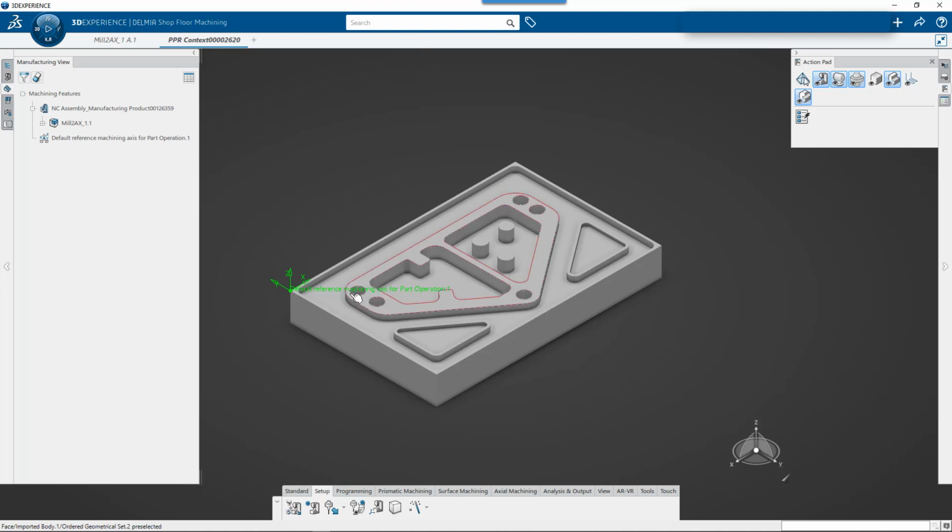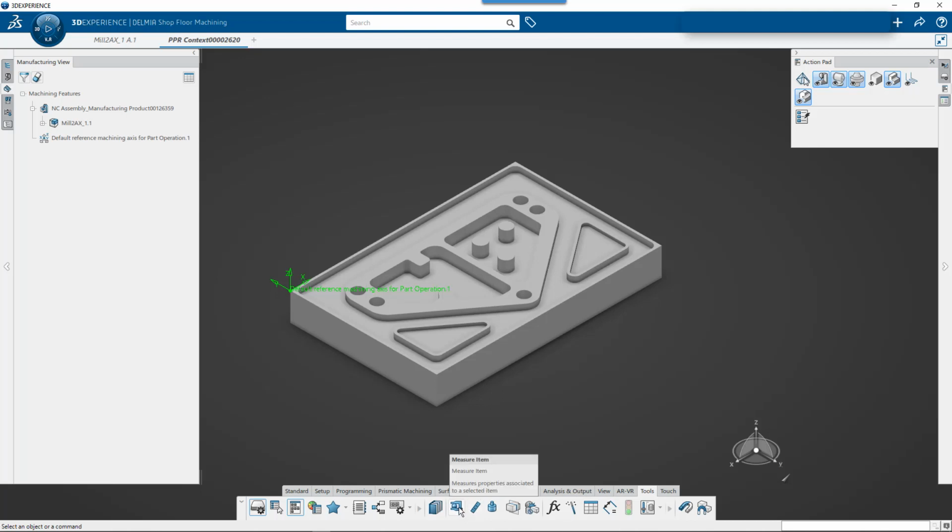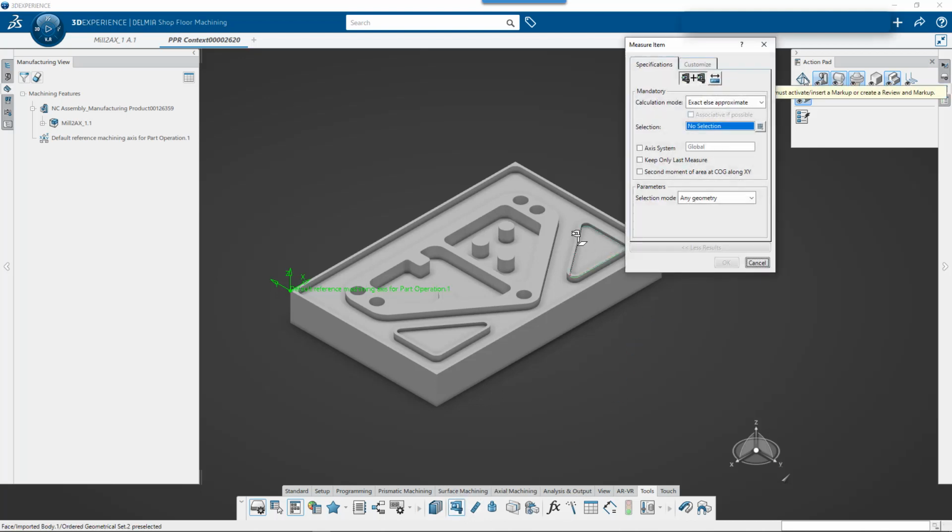And in this lesson, you'll notice we have some holes that we want to drill. One of the things I do want to show you here, if we're not using automatic feature recognition or anything, is some of the options we have down here at the bottom. Under the Tools tab, there are some options for measure. There's measure between, and then there's the dial calipers. If I click the dial calipers, I have the ability to come out and measure different items.